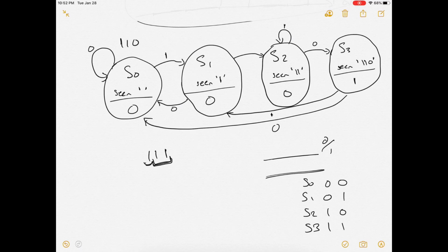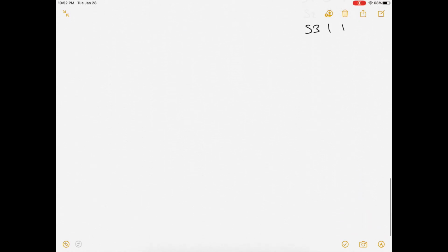So whenever we put in these wires 0, 0, for example, we mean we are in S0. If we put 0, 1, it means we are in S1. We can also give them the names Q1 and Q0. Looking at the circuit we would like to build, because we have 2 wires, so we need 2 outputs and 2 inputs, we're going to have 2 D flip-flops.